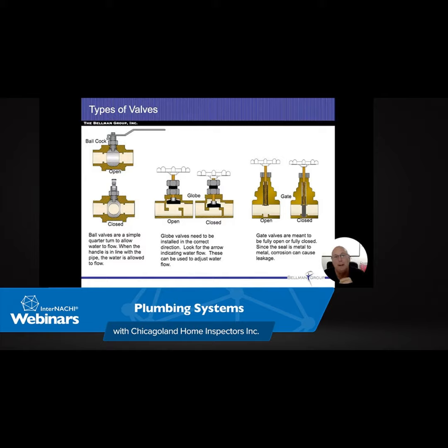Temperature controls. 120 is kind of our magic number for a safe range. And again, this is all how much risk are you willing to take. For us, we shoot water flow with the thermal imagers so we can take a temperature of that coming out of there. But I'll openly admit, even my water heater here is set at 140 degrees. So water that's coming out of our spigots, our faucets, is going to be 140. 20 degrees over the safe range on that.